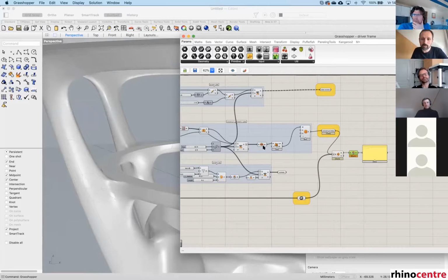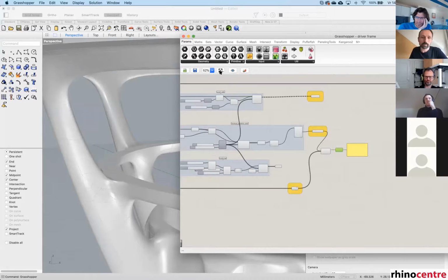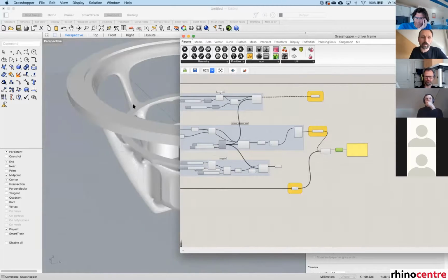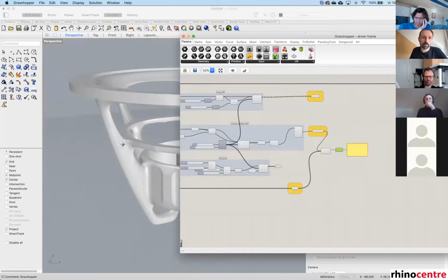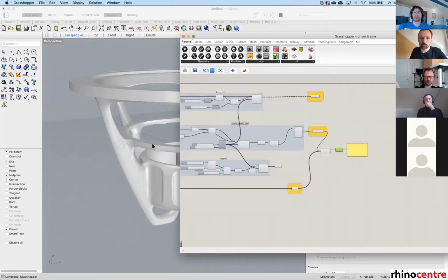that's because converting it from a subdivision surface to a joint subdivision surface in Grasshopper, we need to convert it to mesh, join that and weld the vertices, and then combine it back into a Nurbs model. So it's a little bit convoluted. This is mainly for doing a joint model during the development stage.